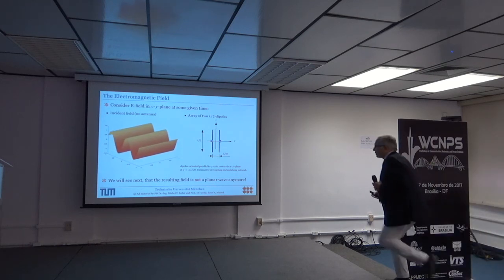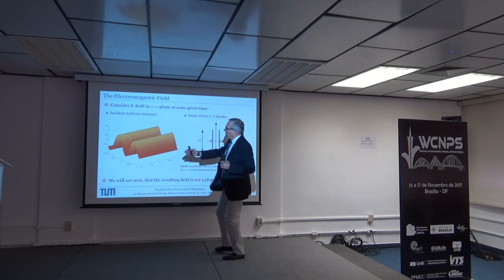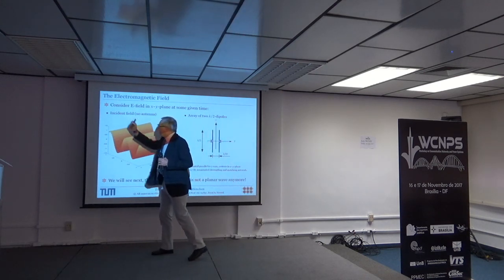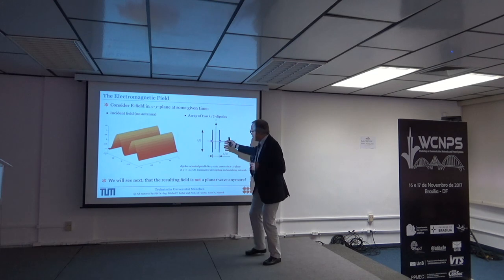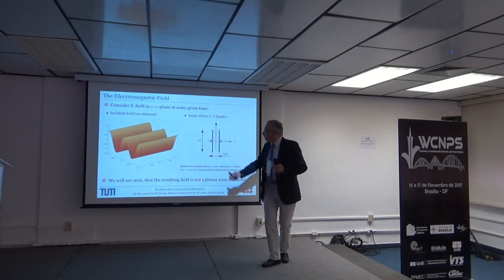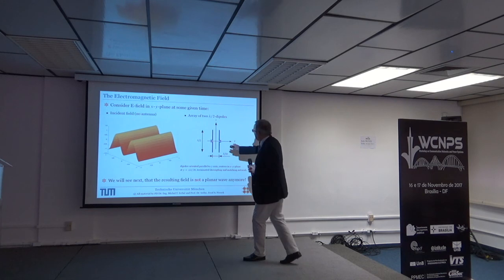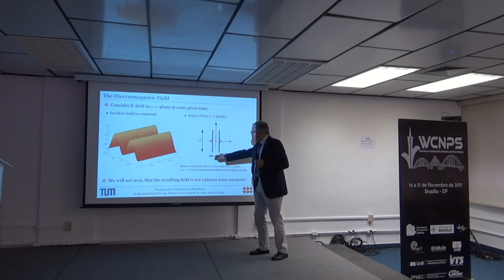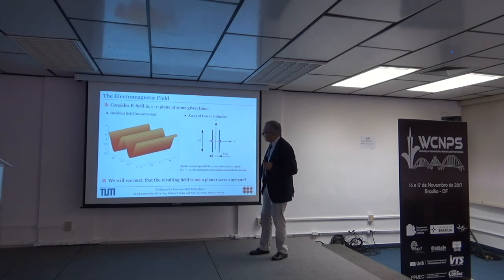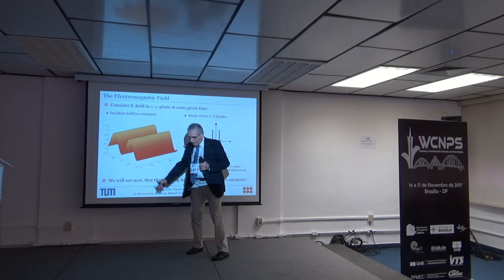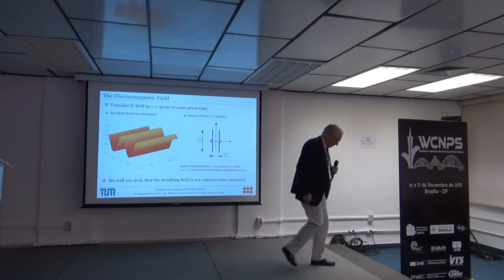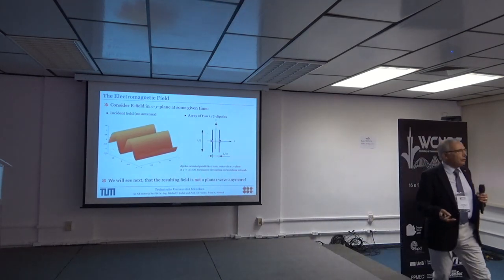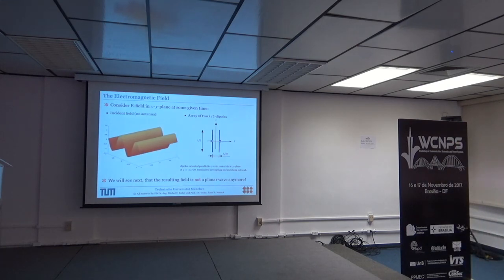Imagine you have such a plane wave with a vertically polarized electric field. So the electric field has only a Z component, and it's coming towards us here, of course in slow motion. If we place these two antenna elements, again, half wavelength dipoles with a distance of 1/10 of the wavelength between them, in the center of that square, and if they're open circuited, then nothing changes, because these antennas are so-called minimum scattering antennas. And if at the terminals there is no current, then there is no current on the whole structure, and then it's simply as if they are not there.